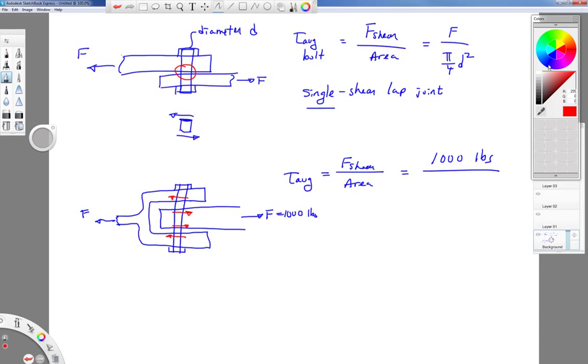This bolt we would say is in double shear, and we would find that area, the total area then would be 2 pi over 4 d squared for the bolt. The bolt has diameter d. So this would be a case of a double shear joint. Now on an exam, I would expect you to know if I write down double shear, what that means to do, and then if I were to give you a picture of a joint that looks something like this, you should know how to handle double shear as well.